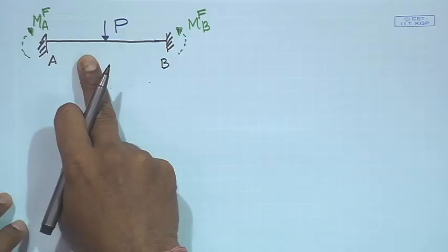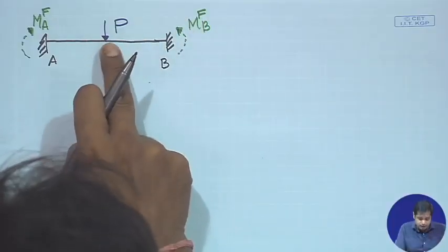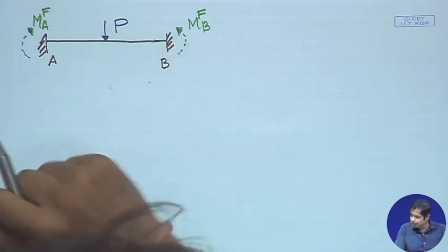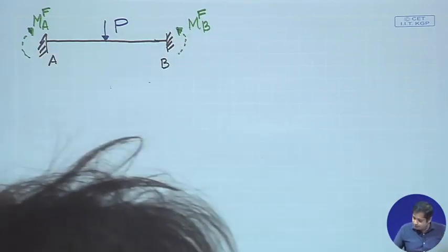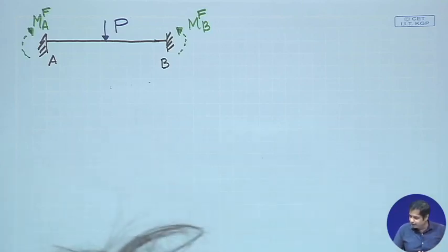So we can apply the force method to find out MA and MB. Again, we have different force methods, mainly the method of consistent deformation, but written in a different form. We can apply the three moment theorem that we discussed last week to get these moments. And what is the three moment theorem?